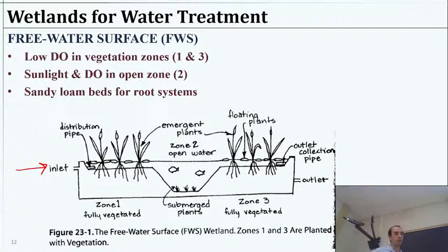Now, for the plant matter, of course, you want good sunlight across all of it, especially for the production of your dissolved oxygen by algae. In the beds, you want something like a sandy loam type soil, so that water can move fairly freely through it. There's not really a big barrier for the roots to get into it, and you're not just having a bunch of fine sediment everywhere clogging everything up. And you want decent water movement to flush through the soil here. That way you're making good use of your surface area, all that space for bacteria to grow and do all that.